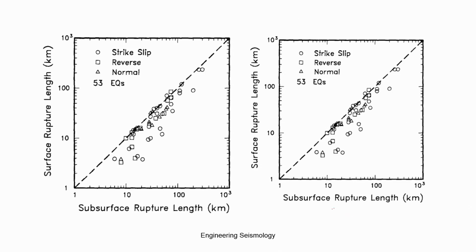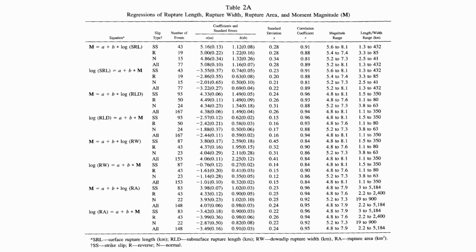Again, this is for another region where you can see the subsurface rupture length and rupture length. So, based on this kind of systematic analysis of the entire global data, they have given a relation between M versus subsurface rupture length and surface rupture length. Okay. The subsurface rupture length is the one which is controlled by the fault and rock in the region.